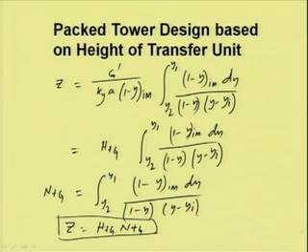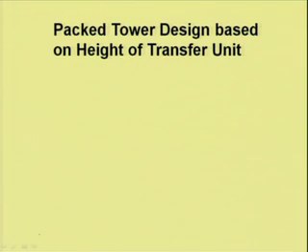Now, this relationship we can apply for liquid concentrations as well. So, for liquid concentration we can write the counterpart of this equation, Z is equal to HTL NTL.